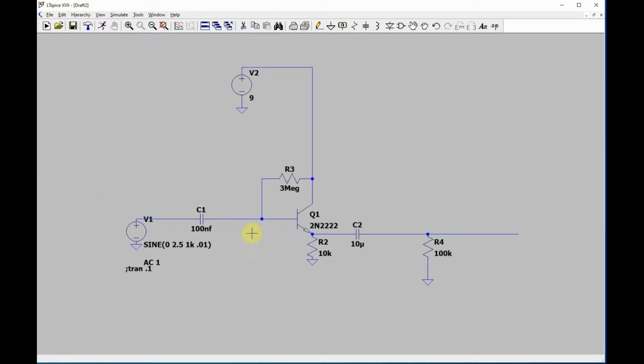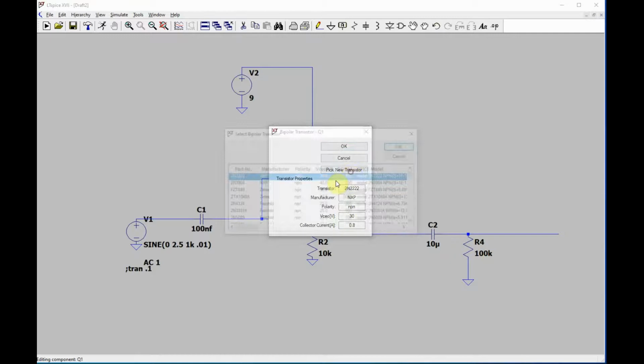So we talked about the input impedance and the kind of the biasing of those different circuits, and I think you should consider the output impedance. Now, an ideal buffer has a signal come in, there's a big input impedance, there's very low output impedance, and it's in phase with it. You know, that was basically an ideal buffer. It just copies a signal. It's like a big block with high impedance on one side and low impedance on the other. So this has very low impedance.